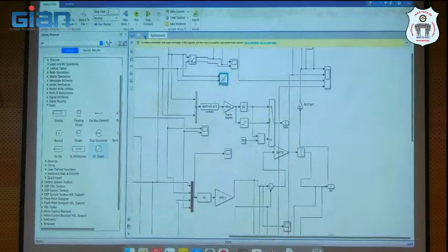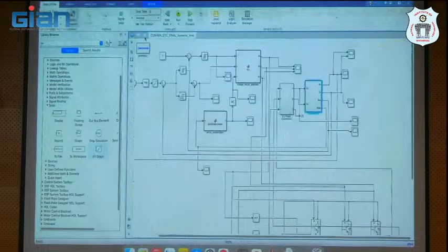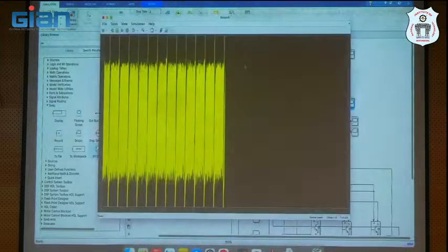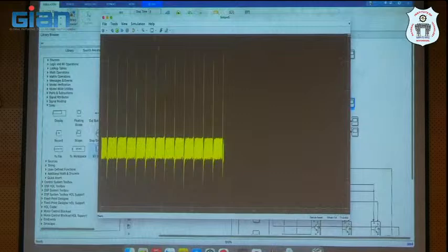If magnetizing flux is like this, you can check your torque profile. Where is the torque profile? See here. You can check, there are a lot of ripples in the torque. This is the torque response. There are spikes, right? Spikes are very dangerous.